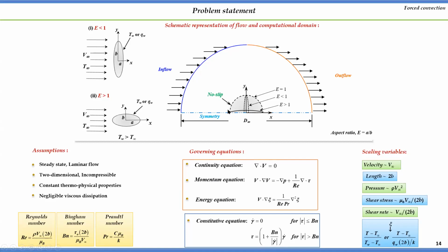We have assumed this object came across the path of fluid, but no boundary disturbs this flow condition. So it is basically considered as an unconfined flow. In order to consider unconfined flow, the domain has to be very large, and we have to impose the boundary condition at the inlet as inflow, at the outlet as outflow, and at the middle plane we are imposing symmetry.